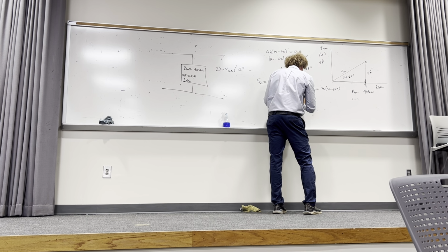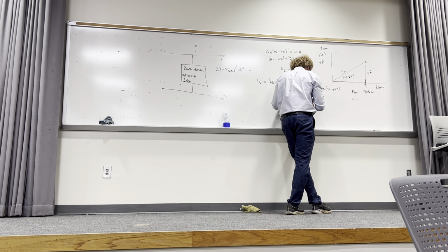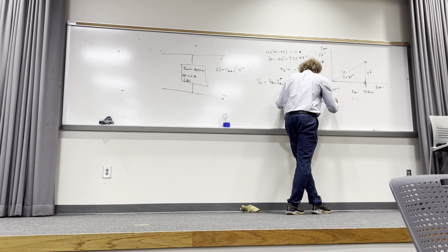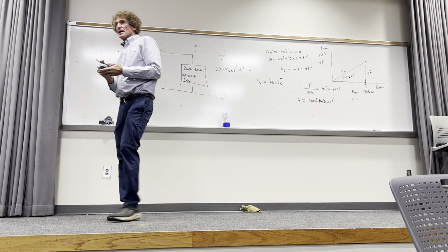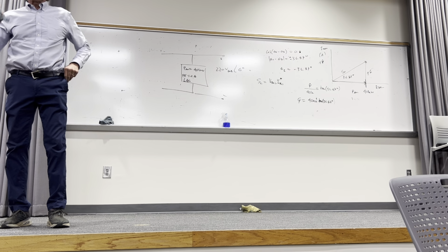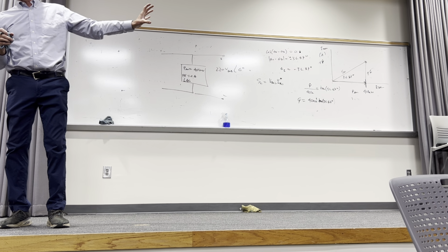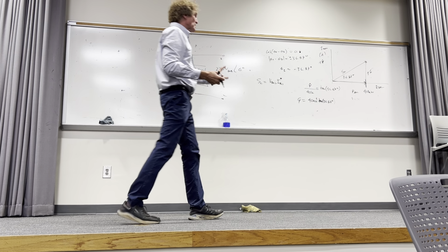And that means Q, or the imaginary component there, is going to be equal to 40,000, or 40 times 10 to the third, times the tangent of 36.87 degrees. First, do you agree with that, everybody? It's not hard to see, but you have to make sure you see this. The only thing I'm trying to do is figure out how much jQ is there based on that triangle. And it's just a right triangle, it's a straightforward thing.